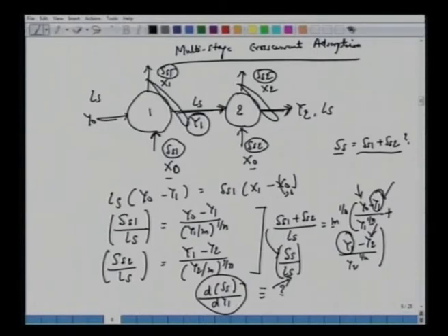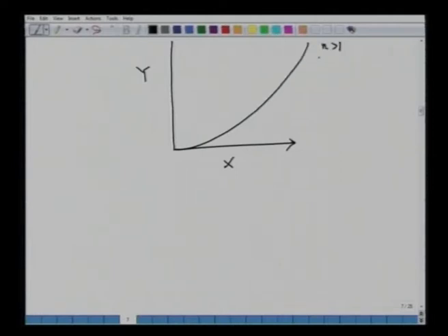Okay, before that let's plot graphically what we're trying to do here. So we have this X, Y equilibrium curve here. Let's say we are using n greater than 1, favorable isotherms. Y0 is fixed. Let's say X0 is 0, so fresh adsorbents. If we know the amount of solid in stage 1, we can take that operating line and we can reach this intermediate concentration Y1. So this would be Y1, this would be X1.